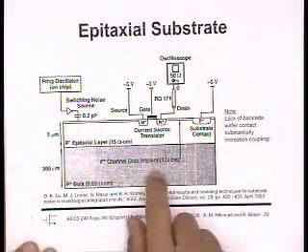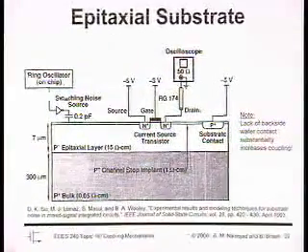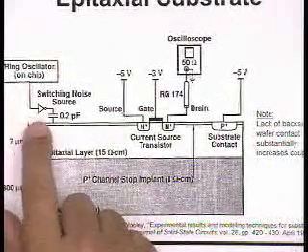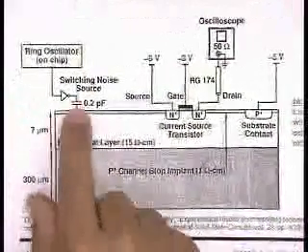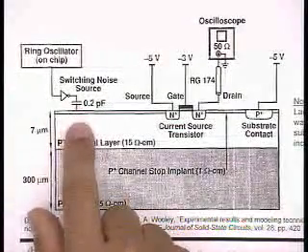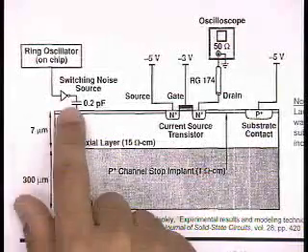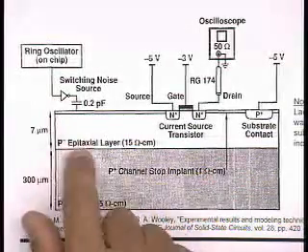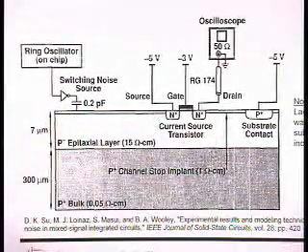In their example, you've got a ring oscillator on chip that's driving a capacitive node. This capacitor couples to the substrate through its backplate parasitic and also through the drains of these devices. The NMOS and PMOS devices are also capacitively coupled to the substrate. In this case, the NMOS is more so because they don't have a well around them.